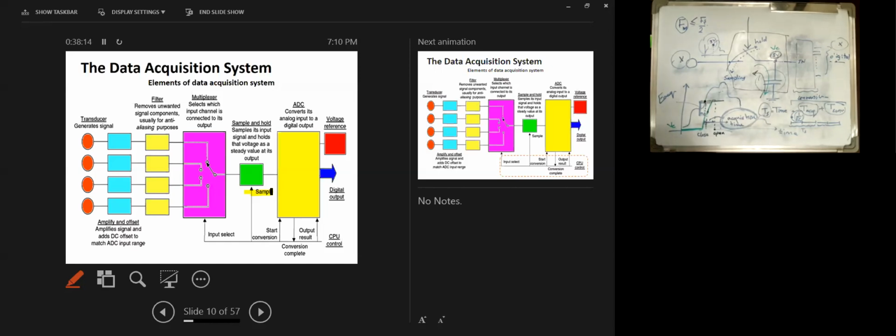And we will see how this is implemented in our microcontroller, how we can control the acquisition time in the HCS12 microcontroller. Okay, so these are basically the components that you might need in a data acquisition system that is capable of acquiring a signal and converting it into digital format. As soon as you open the switch, you can instruct the A2D to start the conversion, as we said, through the digital interface that comes with the A2D.